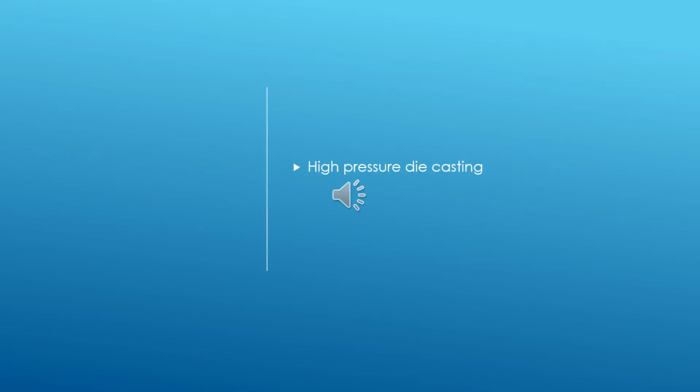Firstly, let's talk about high-pressure die casting. High-pressure die casting, also called HPDC, is a very commonly used process for creating structural components. In this process, a metal die having a cavity with the negative geometry of the part is created. Simple dies usually consist of two matching halves, while more complex dies can add sliding features that create holes and undercut areas. Here are some advantages and disadvantages of this process.